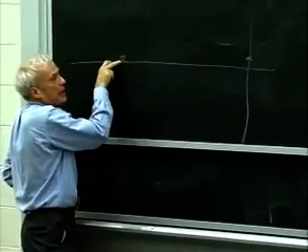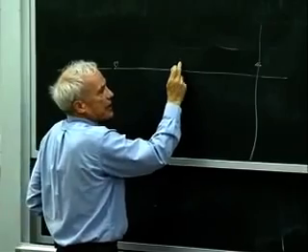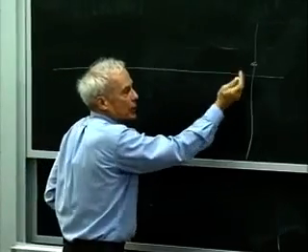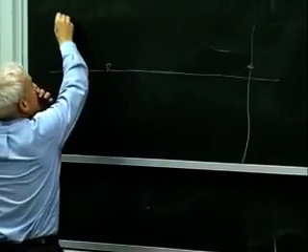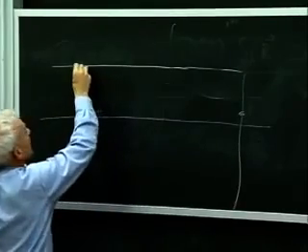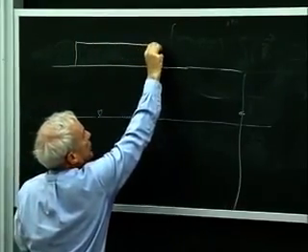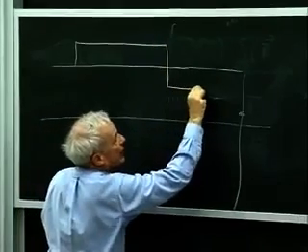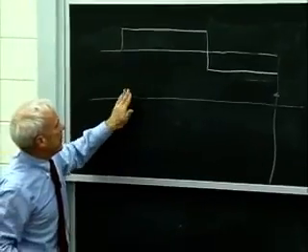Well, it's to hit the accelerator as hard as you can until you get to where you think if you hit the brakes you won't hit the wall, but you'll stop right there. And so the control action involves accelerating as hard as you can until you get to the point where you hit the brakes and decelerate as hard as you can and come to a stop right there. That's the minimum time way to get from here to here.